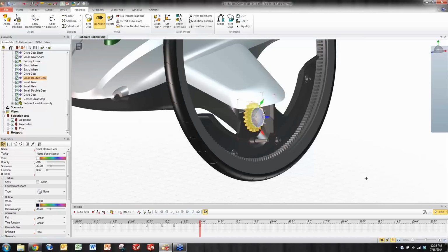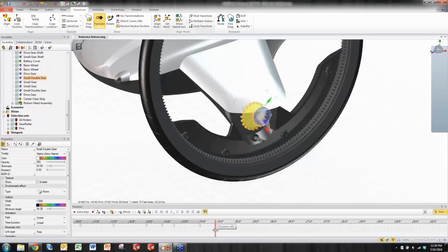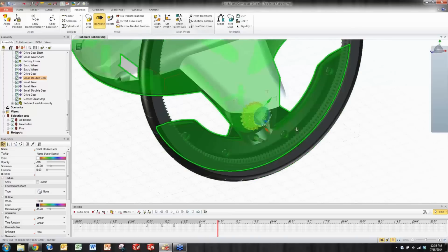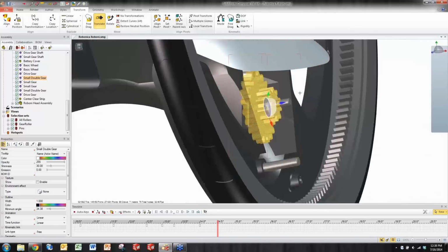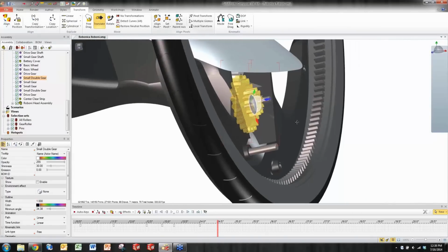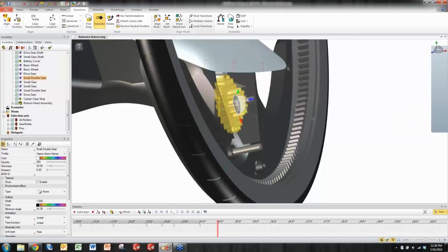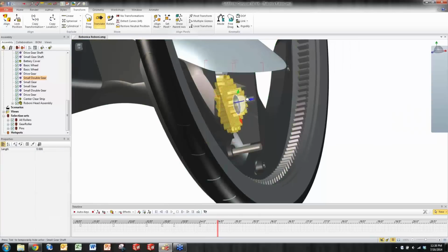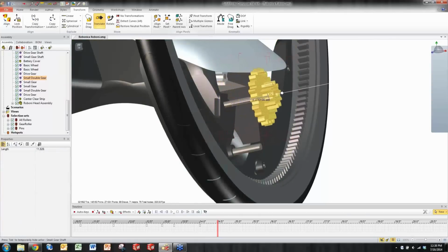So first thing, I've set my location at 14 seconds of where it is right now. I'm going to turn off camera play mode because I want to be able to zoom in and see from the side to make sure that as this thing explodes, it's not hitting this top fender or overlapping geometry as it's exploded. So I'm going to take this to 14.5 seconds. I want it to come out to about here or just off the shaft, and I'm going to go ahead and record.